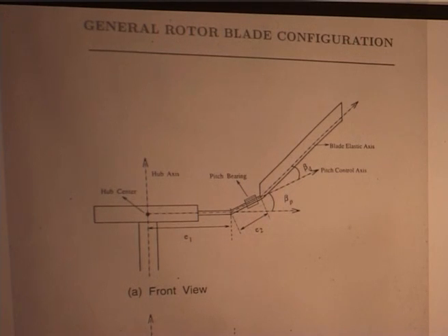and this will have a lot of effect in torsion. So, you see flap, if you look at it, in both configurations there will not be a major change, in lead lag there will be a change, in torsion there will be a lot more change, which will go to pitch link load. Then you say which one is better. Okay. This debate goes on because changing a configuration from one to the other is not an easy task in the actual design. Finally, you live with whatever load comes, and you try to minimize something here and there. So, each has its own plus and minus.